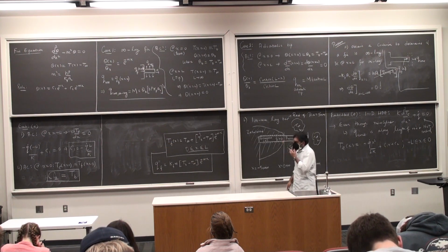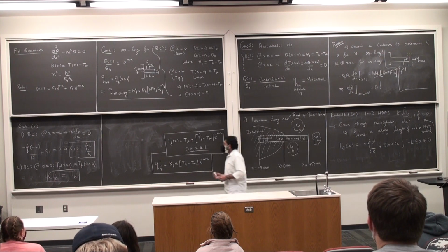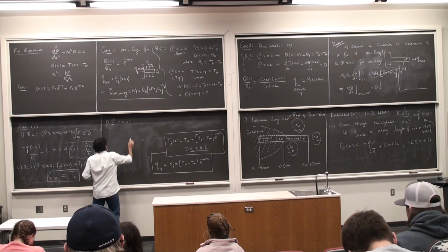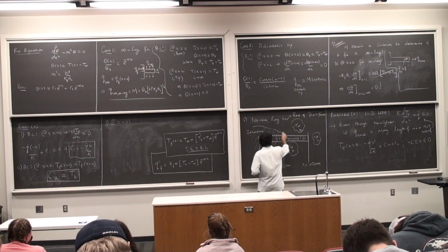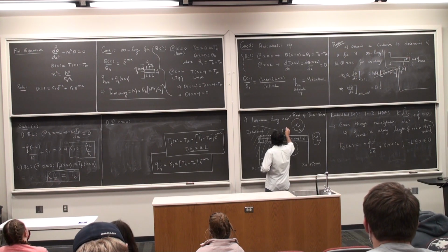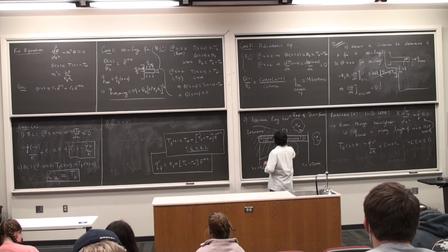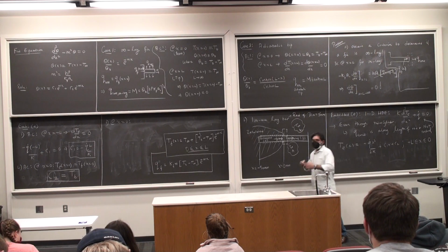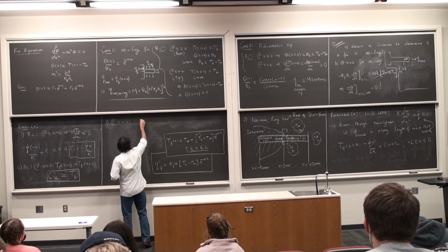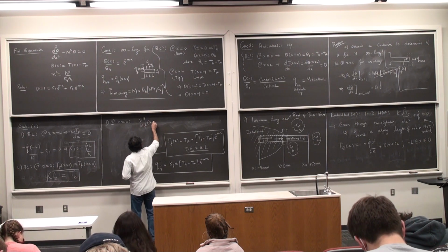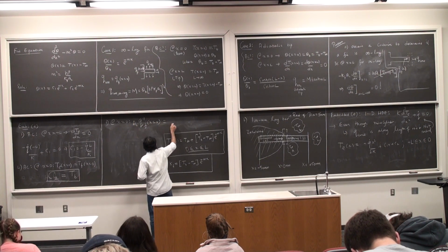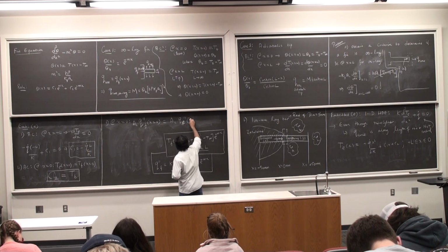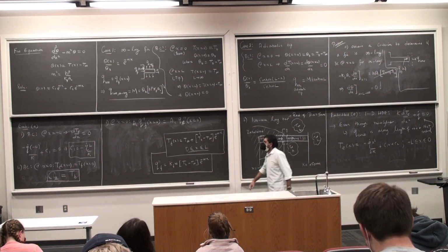I'm going to keep these. There is flux continuity at x is equal to 0. You can draw a control surface and show that if you would like. Whatever is coming in here has to go out, and I'm looking only at the flux balance. Okay? Same cross-sectional area, so, or if you like, Q double prime fin times area of cross section is Q double prime E at x is equal to 0.